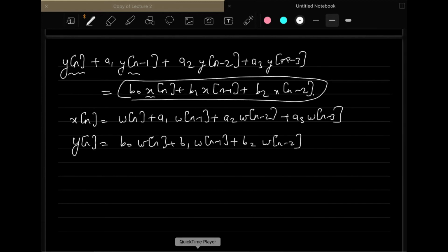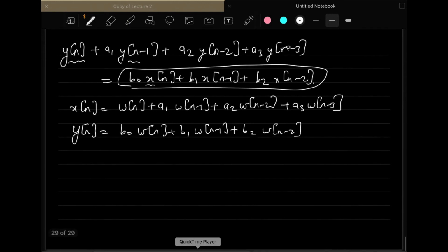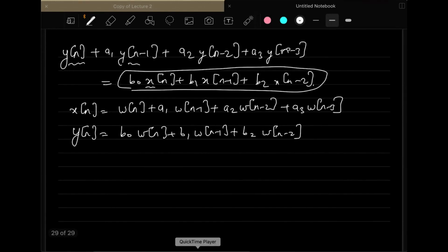If you do that, then you can easily write this in the form of a block diagram, and you will have something like this. It is x[n] here, then we have a plus sign, and then what you get as the output is, let us say, w[n]. Then you have a delay operator D, which takes w[n] and gives w[n minus 1]. So this is basically a delaying operator.